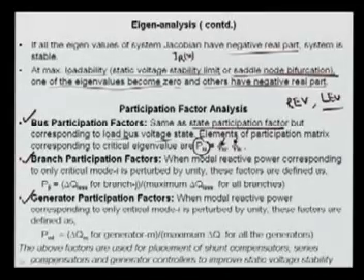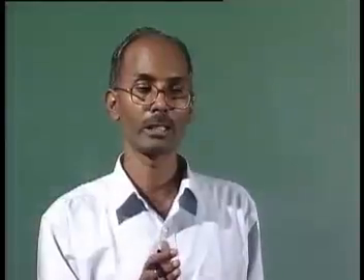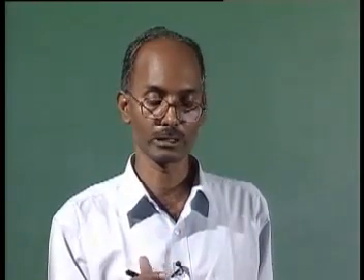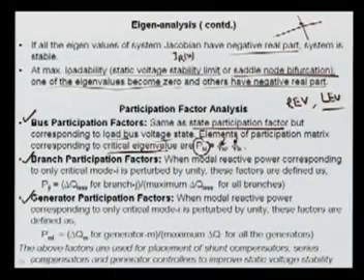The element of participation factor corresponds to the critical eigenvalue. Each eigenvalue will have left and right eigenvectors, and then we can have the participation factor. So we go for the critical eigenvalue, which is the minimum value, that is, in this j axis, how close it is to the 0 point.